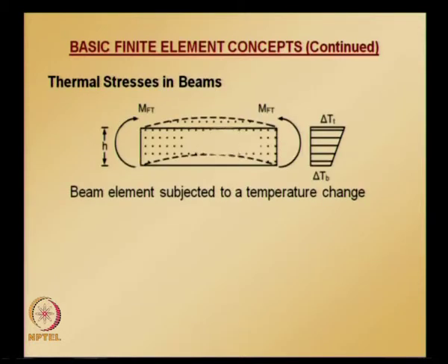thermal stresses. And let us go back and see what we have done in the last class. Considering a beam element which is subjected to a linearly varying temperature over its depth, we developed the equations, and this is the beam element subjected to a temperature change. Delta capital T subscript T is the change in the top surface temperature, delta capital T subscript B is the change in the bottom surface temperature, H is the depth of the beam.